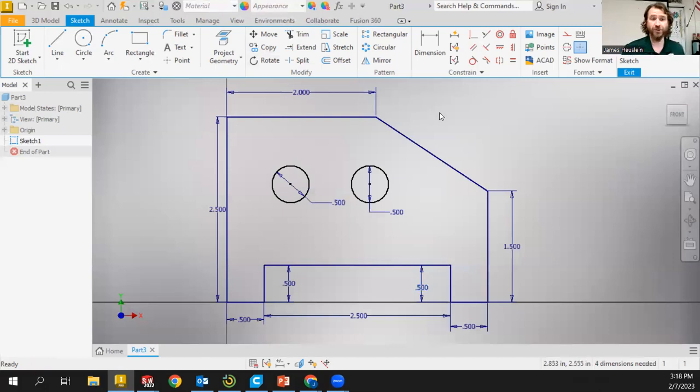Now, if you watched our circle video, you know that a circle needs 3 dimensions in order to be locked in place, in order to be a fully constrained sketch. All the rules are in place that the sketches are going to follow, because these circles can move, right? These circles are still moving. You can see a bit of a color difference, right? We have a blue line and these are black circles. Normally that color difference when we're sketching determines what is fully defined, or fully constrained, and what still needs to be constrained with dimensions or constraining tools, right?